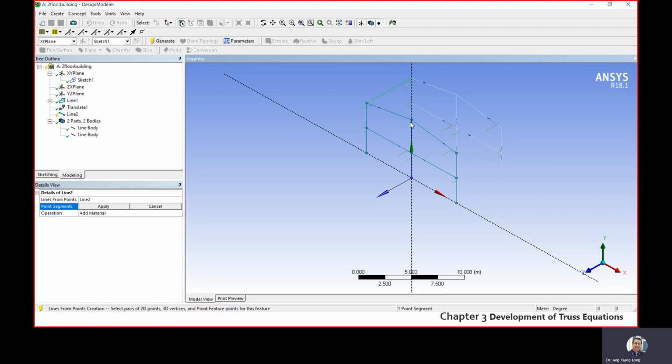So you will connect 2 lines. For the second one, you click this one, then hold down the control key. Second line. Again, left click, hold down control key. Here. Left click, hold down control key. Click here. Left click, hold down control key. Click here. Left click, hold down control key. Here. So we are creating the 6 green lines here.